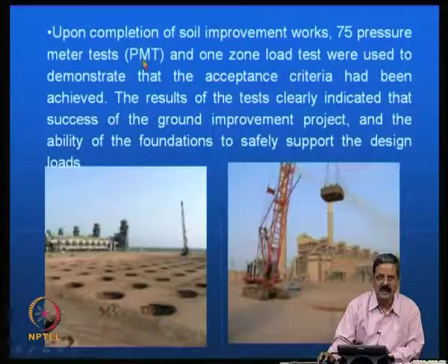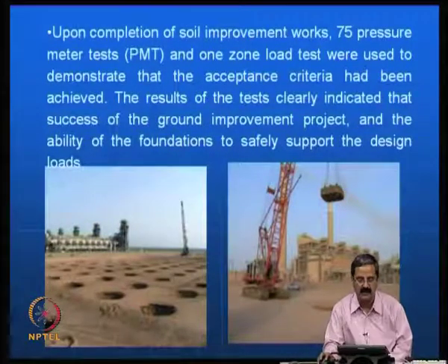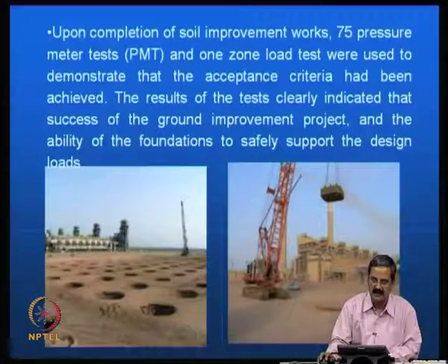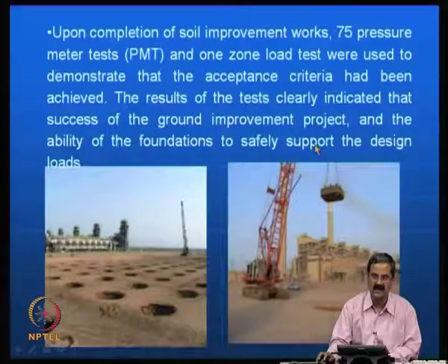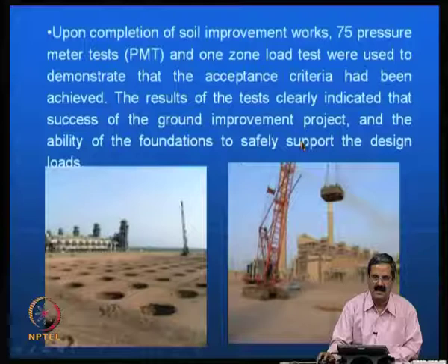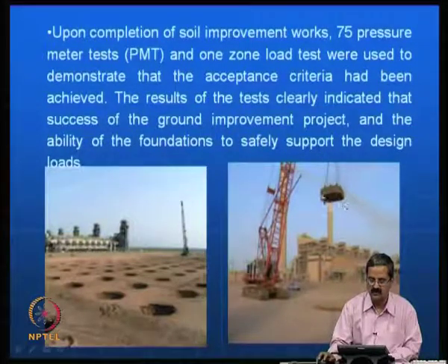You get a parameter called limit pressure from the pressure meter test. Limit pressure is related to bearing capacity, and settlements can also be calculated. So the acceptance criteria of settlements and bearing capacity are met using this. The results clearly showed the success of the ground improvement project and the ability of the foundation to safely support the design loads. Essentially you must be able to give a guarantee for whatever you do. If the soil is so soft, you must be able to improve it to the required capacity, whatever the client asks.